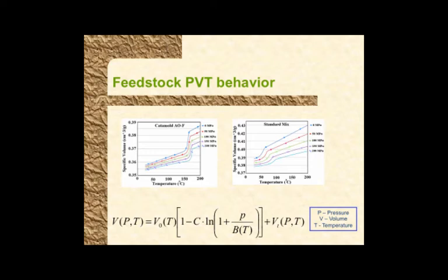It is a slightly more complicated version of an ideal gas law, just accounting for the fact that this is not an ideal gas, it's a powder polymer mixture, and so accordingly, how does volume change as a function of pressure and temperature. In the melt, the specific volume is higher, and in the solidified state, the specific volume is lower. So that makes sense, right? Lower the temperature, lower the specific volume. Higher the pressure, lower the specific volume. It captures those essences, similar to what might happen to an ideal gas.